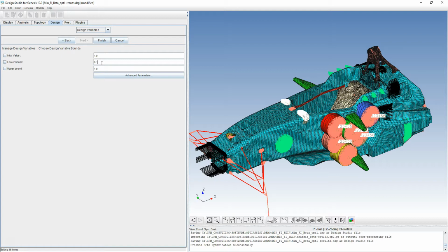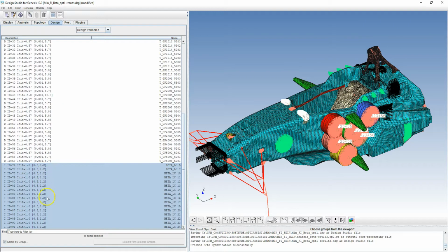And that's a bit extreme really for what we want to do. We want to make ourselves a sensible range. So we can do that by modifying these design variables. And what I'm going to do for this, and I find this is quite a good range to use, is I will give myself a value a little bit higher than my target, because in the optimization there might be some areas I can just identify and resolve manually myself later. And then a lower boundary, which is what I really would like to get to, so 0.8 in this case. You can change these yourself, but I certainly would recommend these settings. If you ensure these are checked at lower bound, upper bound, then you'll find that that's updated for each design variable and therefore each load case.